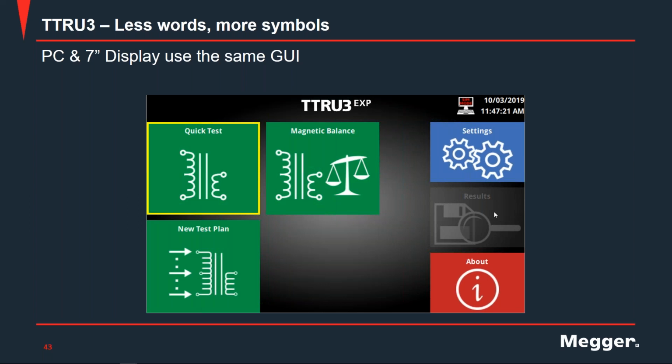Okay, if I may add one point, it's important to mention that the 30-degree phase shift you're talking about, DYN1, represents a phase shift between a line-to-line voltage on the primary side and the line-to-line voltage on the secondary side. That 30-degree phase shift comes from one side being delta, the other being Y. And if we talk about YN0, there's a 0-degree phase shift.